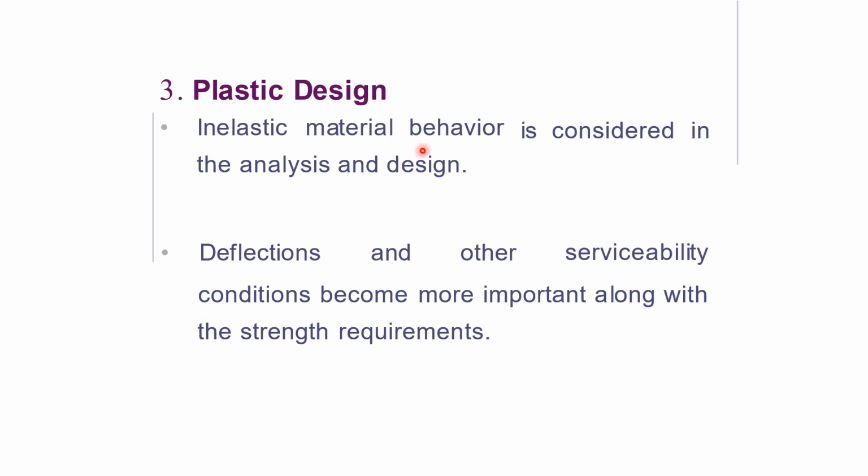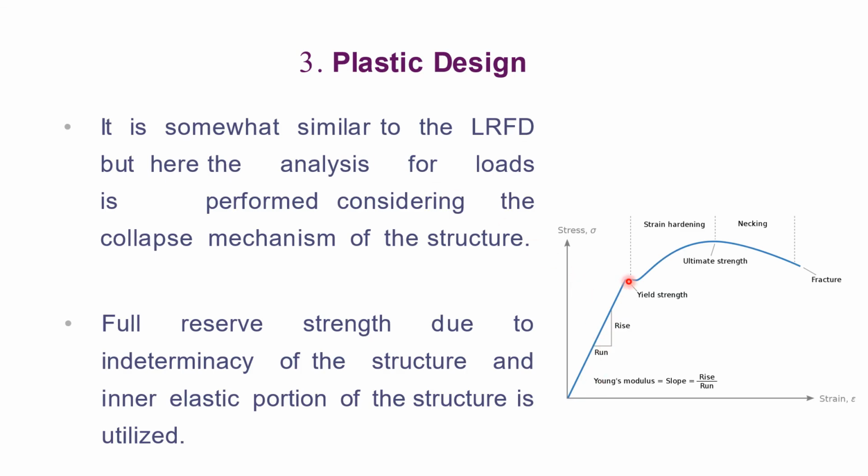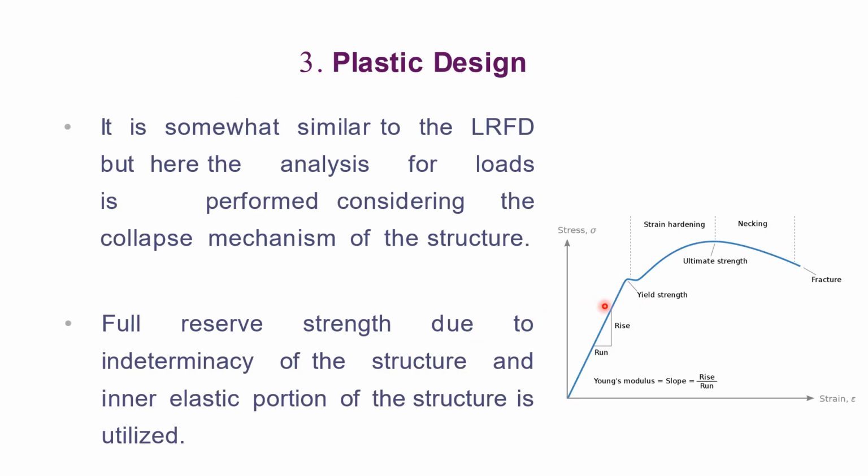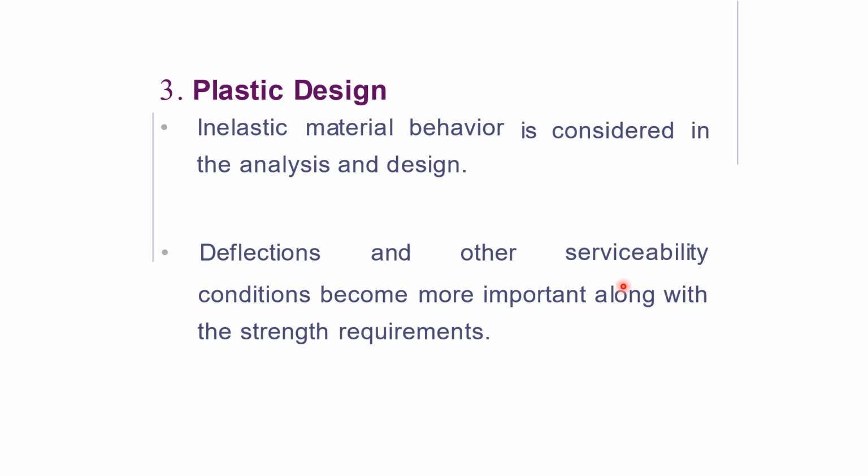Inelastic material behavior is considered in the analysis and design. Inelastic behavior means after the elastic portion there is an inelastic region, so that is used in the design. Deflections and other serviceability conditions become more important along with the strength requirement, because after this there are a lot of deformations to accommodate, to consider, or to control. So the serviceability limit criterion will become more prominent, or more important.